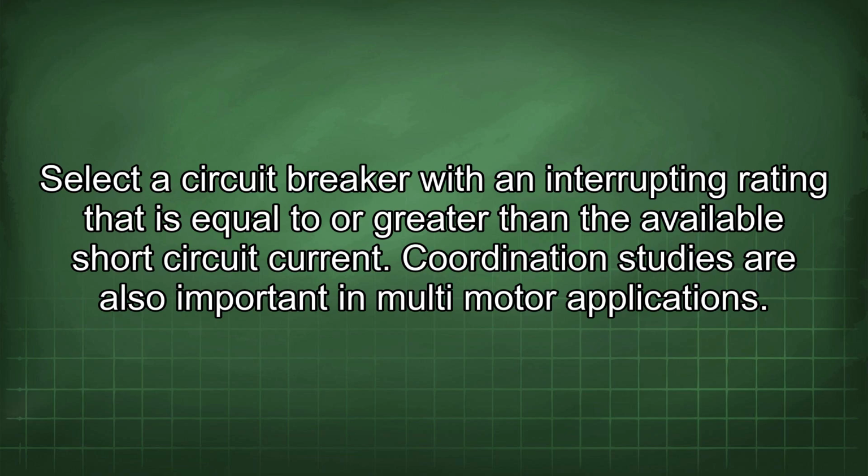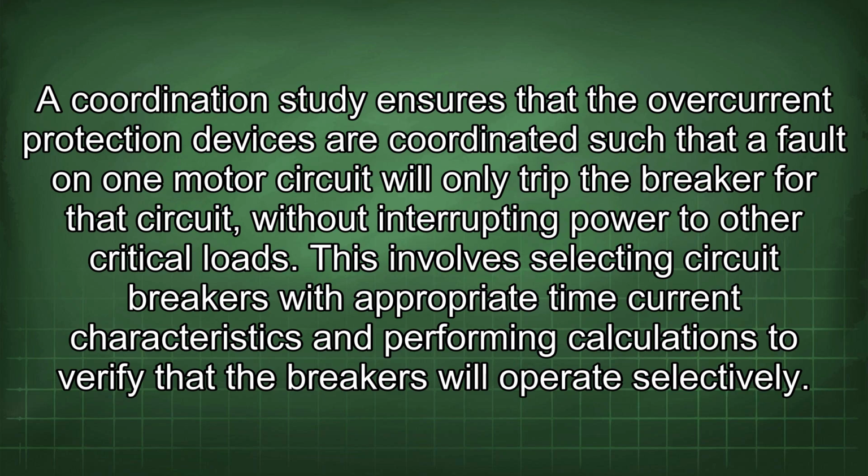Select the circuit breaker with an interrupting rating that is equal to or greater than the available short circuit current. Coordination studies are also important in multi-motor applications. A coordination study ensures that the overcurrent protection devices are coordinated such that a fault on one motor circuit will only trip the breaker for that circuit without interrupting power to other critical loads. This involves selecting circuit breakers with appropriate time current characteristics and performing calculations to verify that the breakers will operate